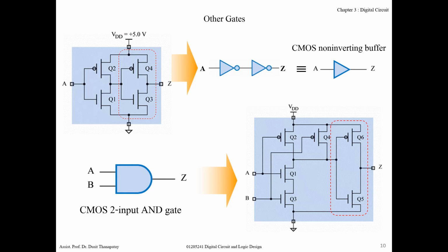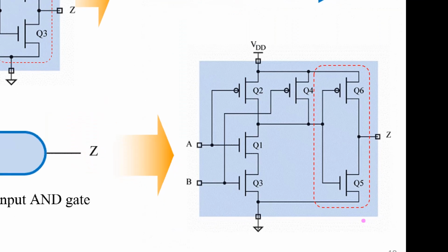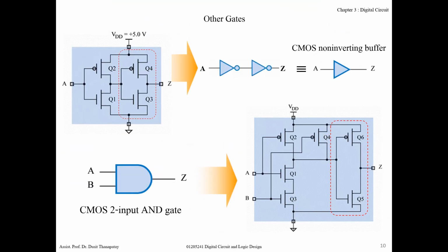So if you can remember the CMOS pattern for the inverter or something like that, you can do the circuit analysis easily. Please remember, it's pretty easy. For example, for an inverter, one of these connects to VDD, this one connects to ground, this one connects to the control signal, and the output is from here. Okay, that's all for today.